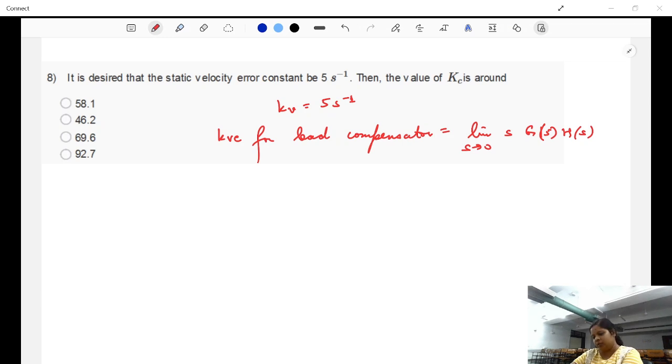So there was something in which we manipulated the closed loop transfer function so that we get an expression related to E(s). So Y(s) upon R(s) was broken into some other parts, which gave us a transfer function corresponding to E(s) upon R(s). And from there, we tried to find out the steady state error.